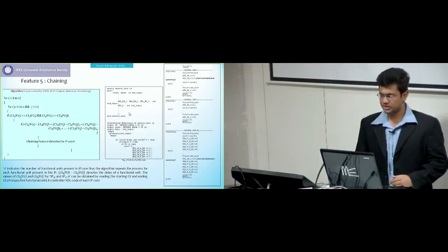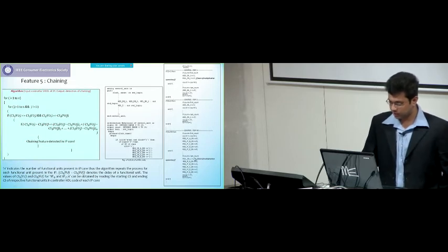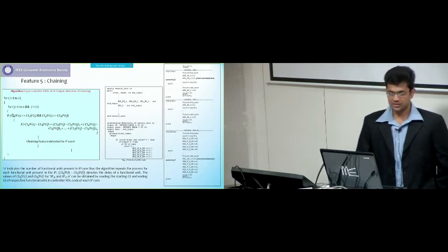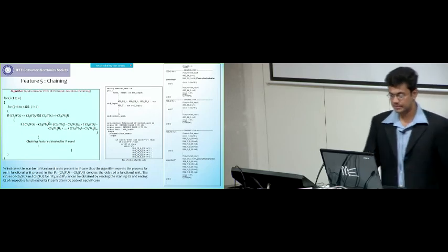As you can see, the signal multiplier enable 1, which has been declared in the entity portion of the VHDL, when it is 1, indicates the start of the multiplication operation, and when it is 0, that is, it is disabled, it indicates the end of the multiplication operation. So what we are seeing is that it starts at control step 1 and finishes at control step 40. This is how we can get the information of the variables CSS and CSE when we use this algorithm to detect whether chaining exists in the HDL file or not.